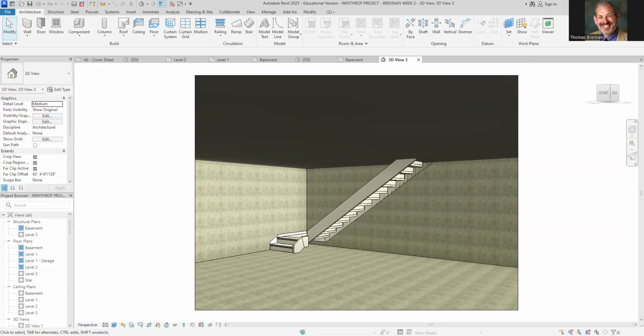Also, when I look at the basement, I still have the underlay so I can see parts of the first floor. Is there a way to get rid of that? Yeah, your basement walls. Let me take a look here. So you're talking about these walls right here? Yeah, I can see the first floor. See, it says -1 foot there? That's why. Those don't need to be -1 foot. And so you're making wall 0. I'll just go ahead and do these one at a time. And that should fix that.